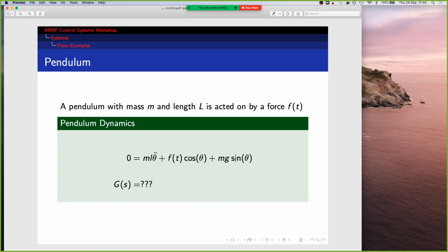Yeah, exactly. So any small perturbation of my regular pendulum is going to take it back to the equilibrium point. For the inverted pendulum, that's not true. Any disturbance is going to take it away from the equilibrium point. So that is an inverted, unstable system.